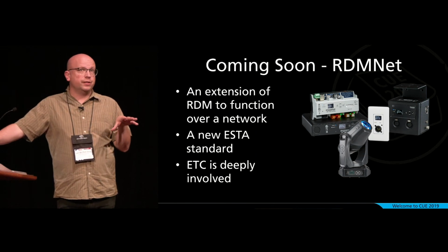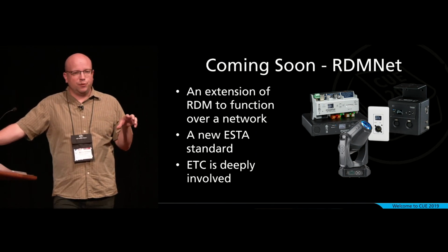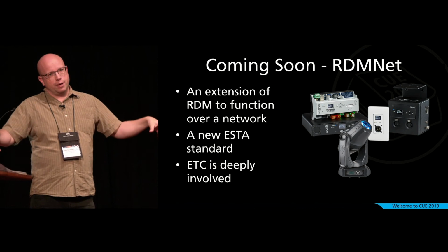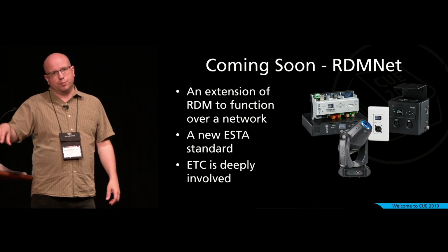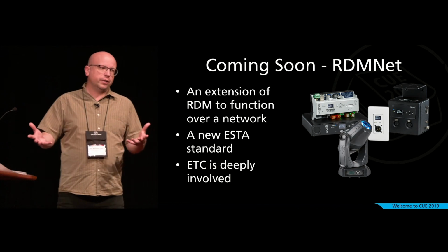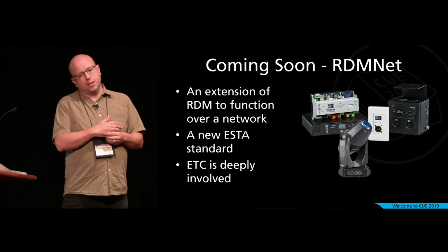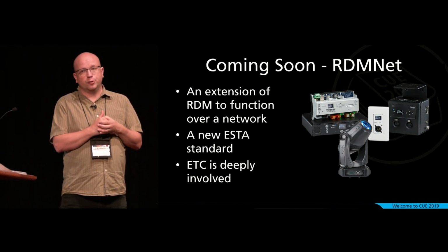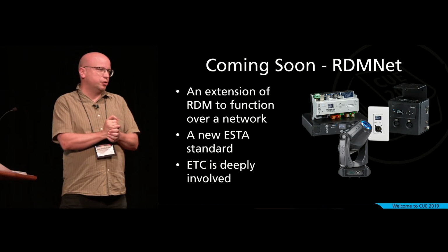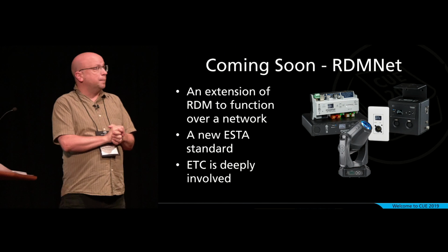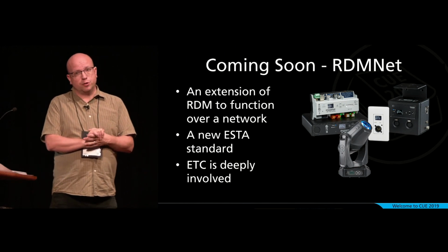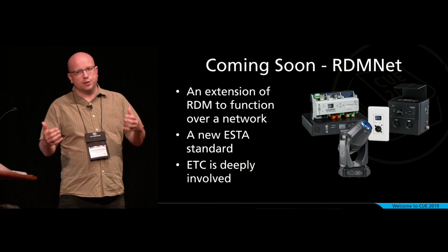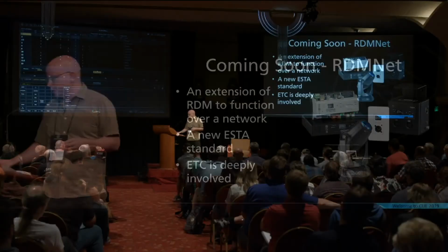The other thing that's nice about this is, although we're calling it RDMNet, if you have a device that you want to configure in an RDM-like way and an RDM controller, they can still both be on the network. You don't have to go via a physical DMX cable. So a media server, for example, that just has a network connection, you'll be able to configure using RDMNet. So this is the big thing we're working on for the future in networking. We're very excited about it. We're really hopeful this will improve interoperability across the board, because that is obviously what everybody wants. And it also should be quite simple to interact with this. So again, there'll be some possibilities for people to do cool stuff that we haven't thought of yet using RDMNet. So that's where we're going in the future.